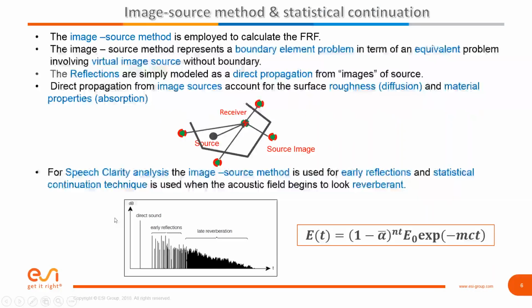We should mention that the general formulation for speech clarity hasn't changed from previous versions of the tool. We're using a transient version of ray tracing to get the direct sound, that first direct path from source to receiver. There's only one. Then you have some early reflections off of the first bounces, the first faces. You start to lose a little bit of energy, but not too much. And then finally, you have late reverberation. You have energy that's reflected a couple of times, had a lot of losses, and you get into a lower steady state kind of reverberant regime.